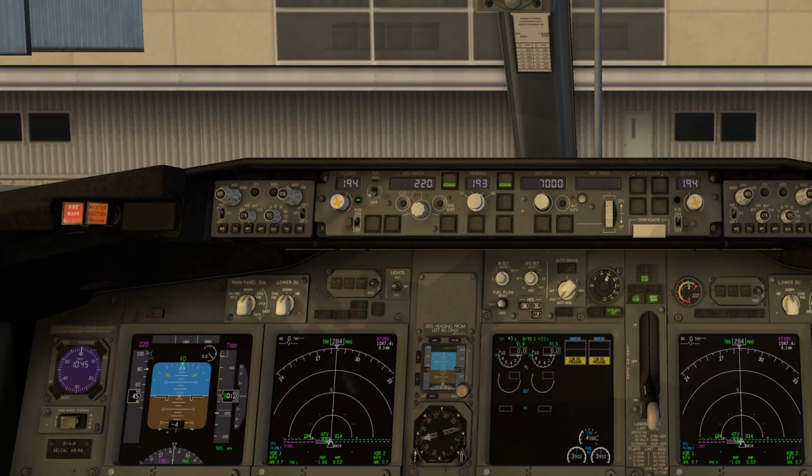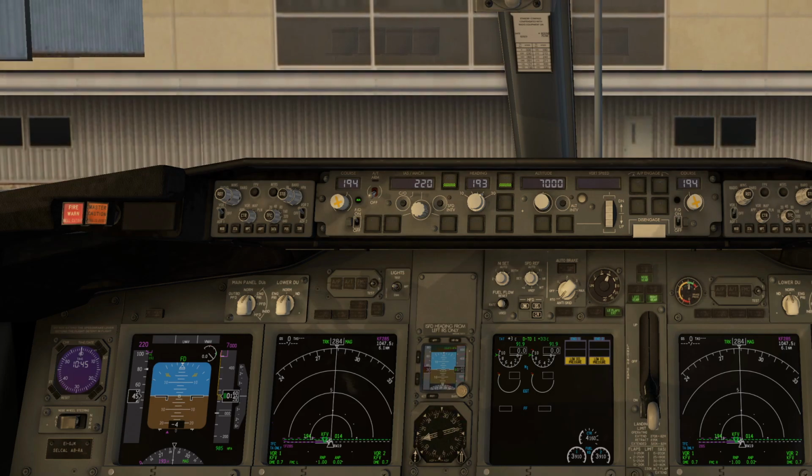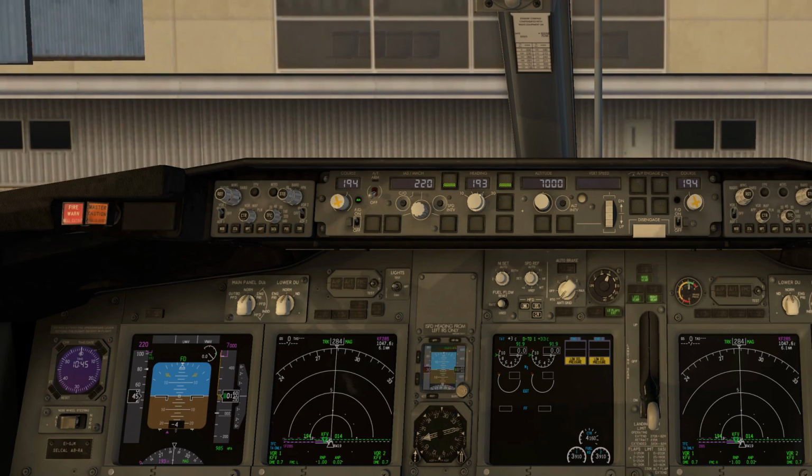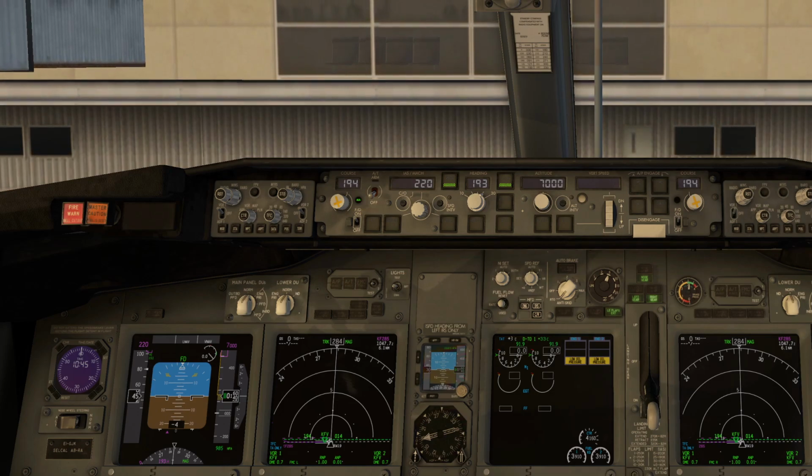And when the pushback is started, we will start the engines, commencing with the engine number 2. So connected and bypass pin inserted. Release parking brake. Parking brakes released. Starting pushback, and you may start engines.